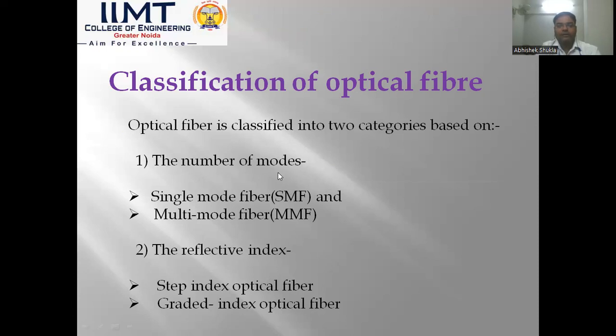Modes means the number of reflections that occur, meaning whether it requires any reflection or no reflection. So it divides into two categories, single mode fiber and multi-mode fiber. According to refractive index, meaning the change in the refractive index of the core and the clad, we can get step index optical fiber and graded index optical fiber.